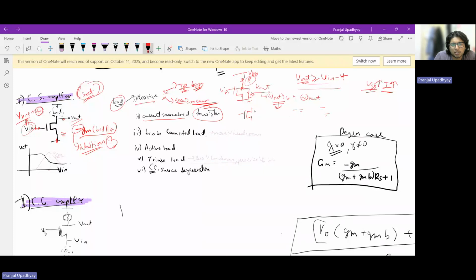So the thing here is that the transistor will allow bias current to flow normally for bias voltages, and when small signal current is concerned, it will also offer high impedance. So it is a win-win situation for us, right?